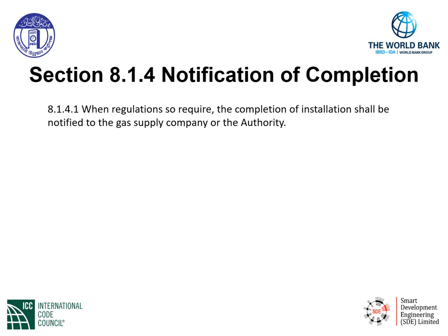Notification of completion. Section 8.1.4.1 gives us, when regulations so require, the completion of installation shall be notified to the gas supply company or the authority. So whenever we have a new gas system installed, we need to notify the authority for proper installation, maybe inspection, testing, and startup of the gas system.